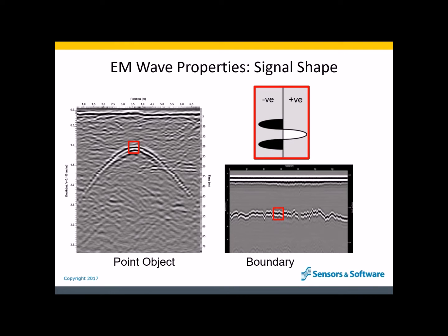It has troughs and peaks, typically 2 troughs and 1 peak, but it could also be 2 peaks and 1 trough. It doesn't really matter. The point is that reflections mimic the GPR signal. Reflections consist of these 3 bands of signal together. The white band has no meaning independently of the black band. Together, all 3 bands represent the reflection.